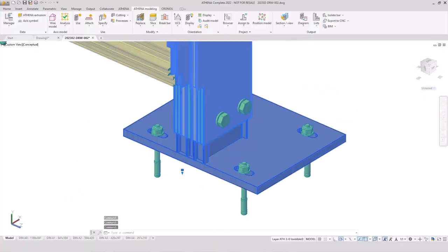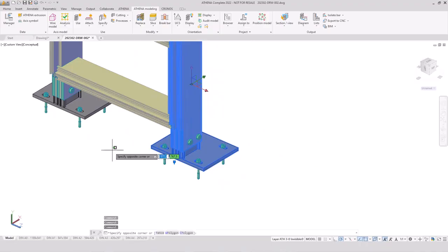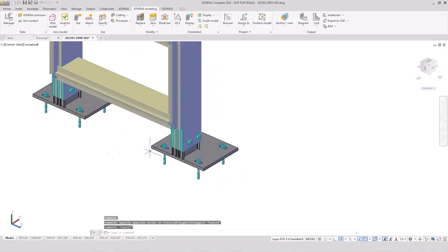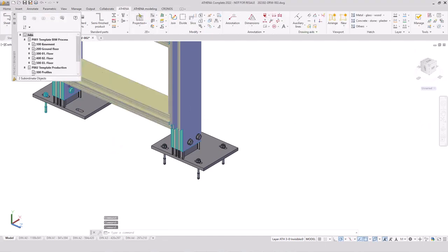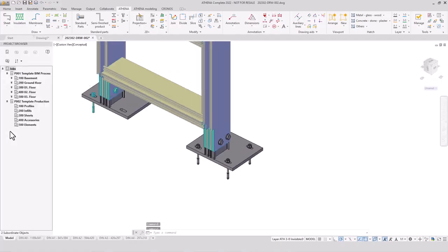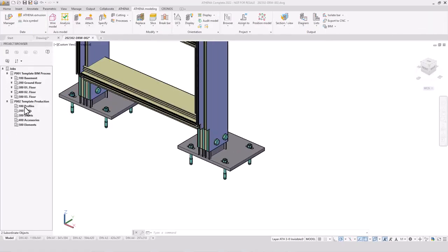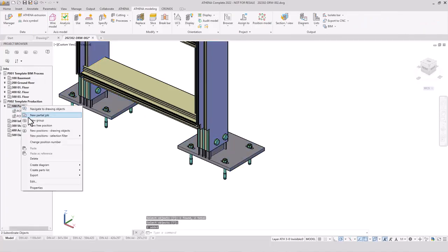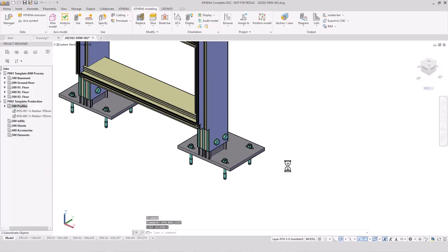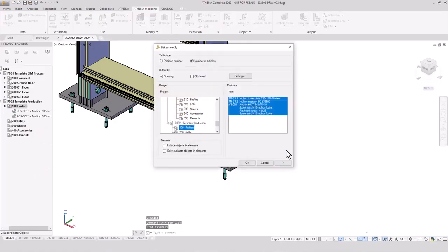I think it's a very high detail assembly group. But for example, if you want to export this model as an IFC file, it's also possible to select a lower detail level. That is better for the export, since the information is the important thing in an IFC file.